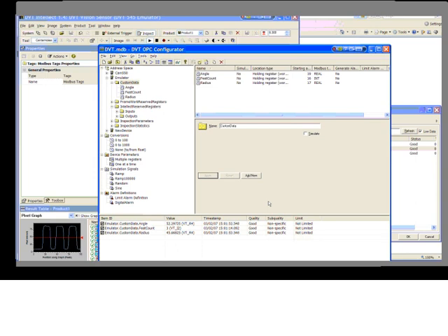If we delete, for example, one of these tags, the value will still be there. It wouldn't change at all because the registers are still there. But if there is some sort of Ethernet problem, then you would see that quality drop, obviously, because we start dropping those values, and the OPC server can't get to those values. But in general, this is a good, not good type of situation.